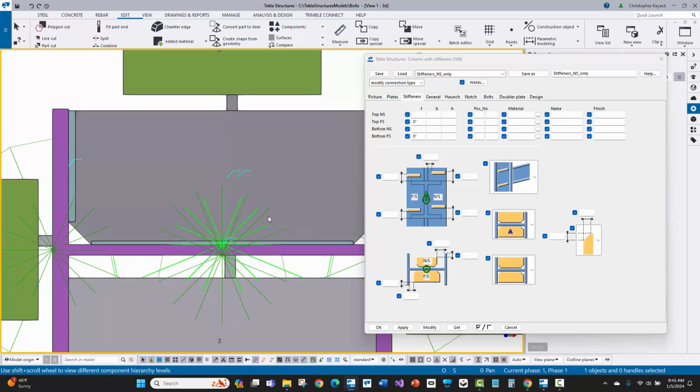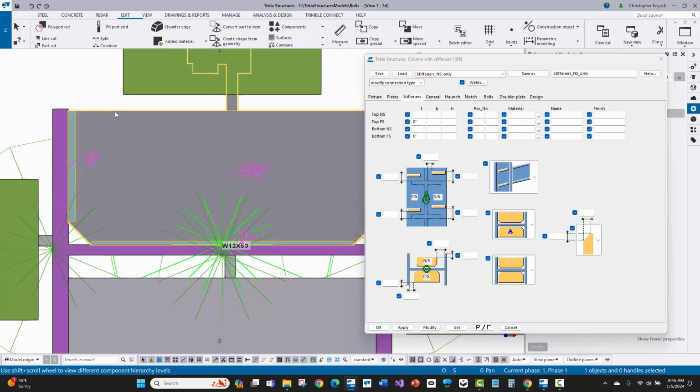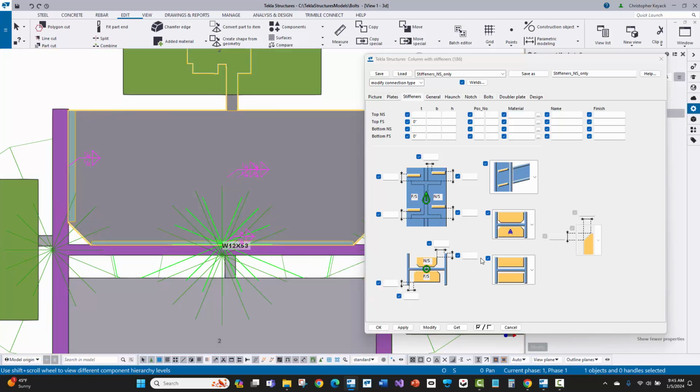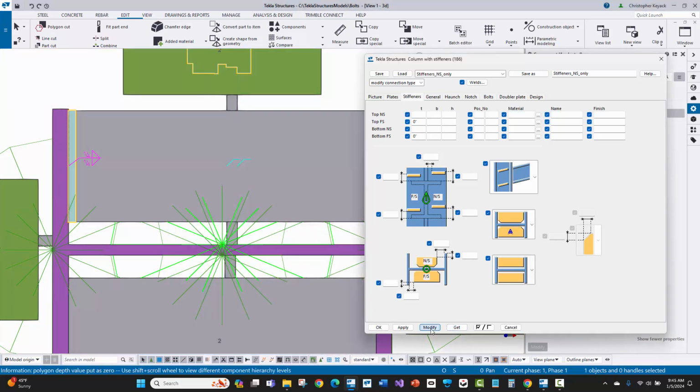So unfortunately, this rounding calculation that's happening on this component happens before it sees that it needs to only go to the flange. So it's just one unfortunate thing here related to this. And that's why I'm getting that strange kind of number. Now I'm going to switch my selection back to components. I'll select on this. We'll modify it back to go to the flange only.